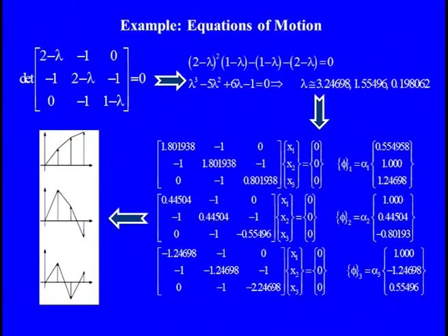So, now we can simply find out that these are the relative positions, and if we want to plot these features into the real mode shape diagram, then we can simply find that this is the way. The first figure shows all three elements, which in this equation is phi 1 2, 0.55, 1 and 1.2. They are absolutely in the same phase, and the masses are arranged in this direction.